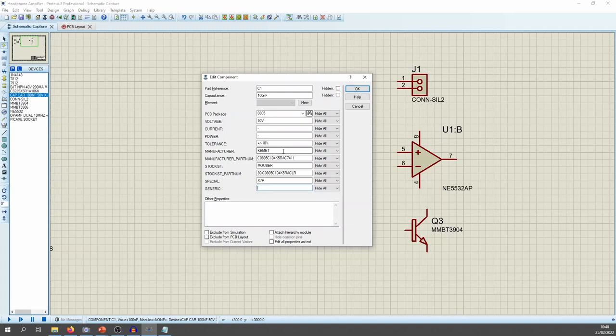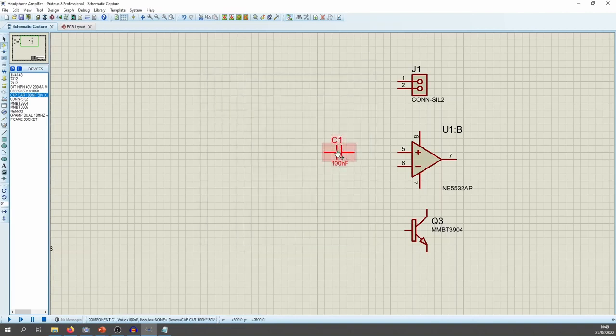So in that case, this particular part, because it's a bypass cap, and we've already filled it with all of the important details, we can actually set that as yes. This time, we're happy for that to be generic. Don't save yes in the library, in that field. Only edit. So when I put yes there, I've only put yes to this particular part on the schematic. I've not saved it in the library. Because it's on a case-by-case basis.